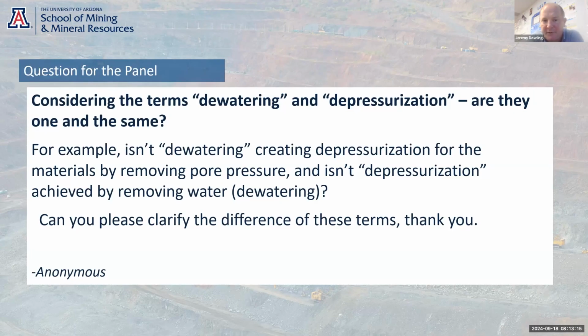But it's also true that if we are doing a dewatering operation, we would expect the removal of the water and the lowering of the water table to have a beneficial impact on the pore pressures in the pit slope. So if we're undertaking a dewatering program, there's always some overlap and some benefit gained with controlling the pore pressures in the pit slope.